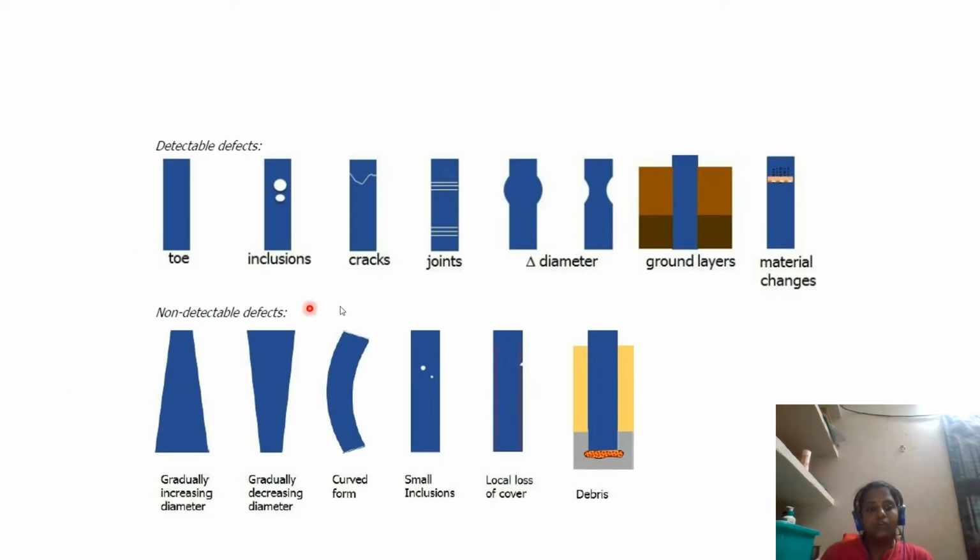In a low strain test, sometimes we will not be able to detect a few defects, like a gradual increase or gradual decrease in diameter, if your pile is cast in such a manner.